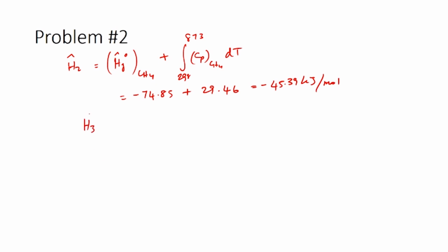So, H3 cap can be obtained directly from the tables which are available for combustion gases. So, you have hydrogen gas which is present in the final condition at 600 degrees Celsius. Taking that from the reference state, you can calculate this and this value would be 16.81 kilojoules per mole. And H4 cap, here again you have carbon monoxide formation and then heating of carbon monoxide.